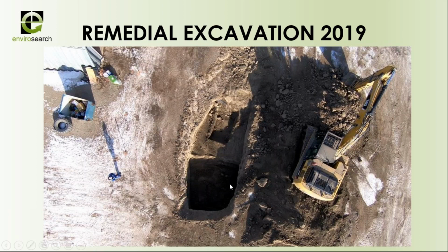So we were able to get lateral and vertical delineation in this north part of the excavation sooner. So then we were able to bench the excavation and save excavation time, but also reduce the amount of digging that we were doing on site because we had confirmation that we had obtained closure sooner in this north part, which had corresponded to where that contaminated borehole had been drilled previously.